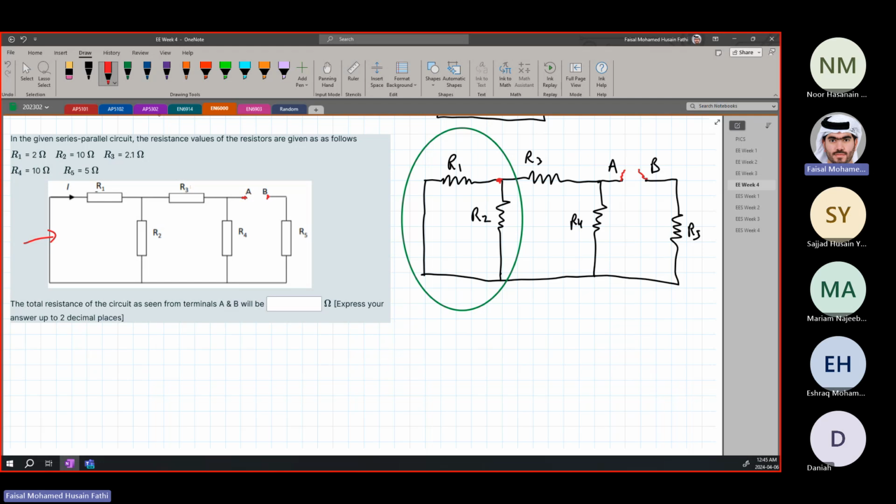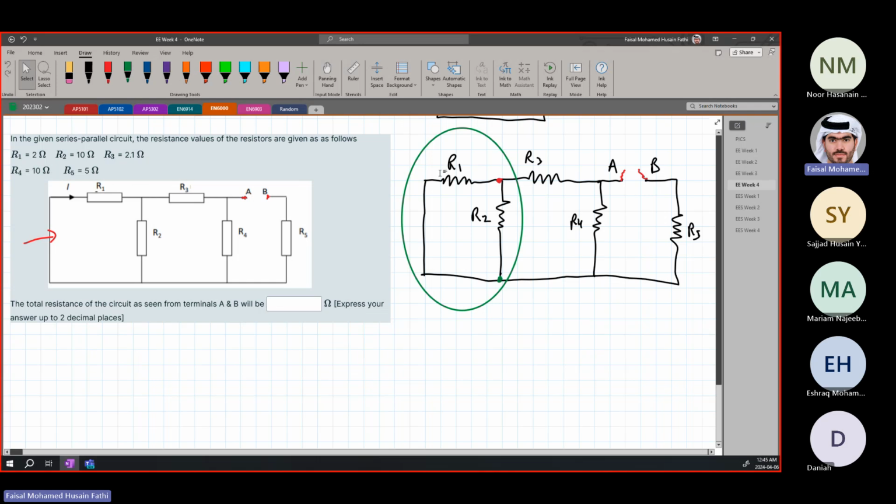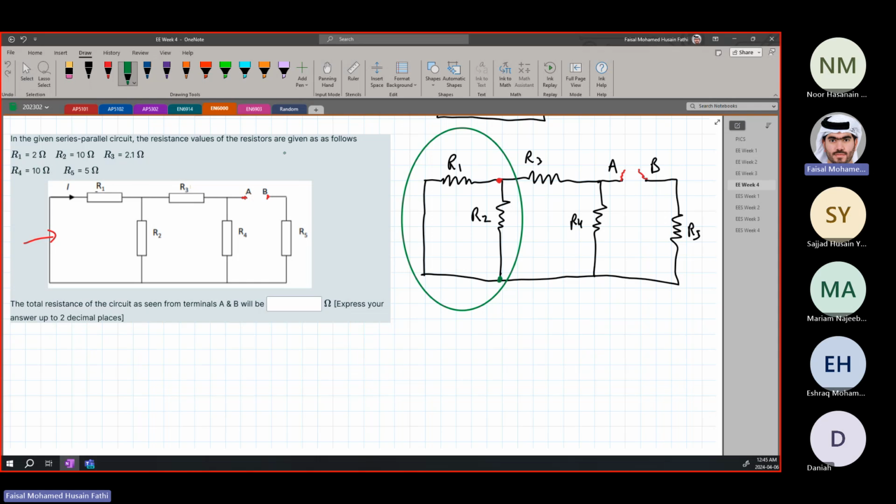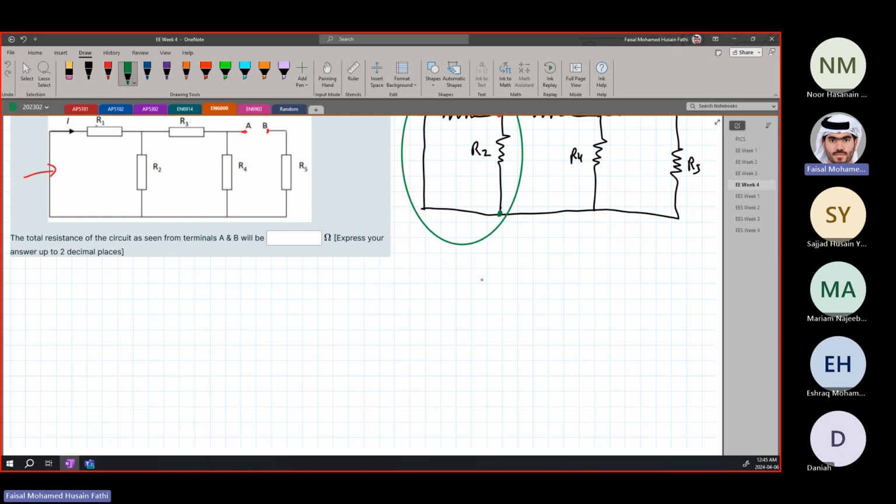They're connected once here, they're connected once here, no. Right or not? Keep in mind, do not get confused just because you see this at the top instead of on the side. It doesn't mean they're not in parallel. They're connected at two separate points. Remember, these are just wires, okay? I can draw the resistors like this too.